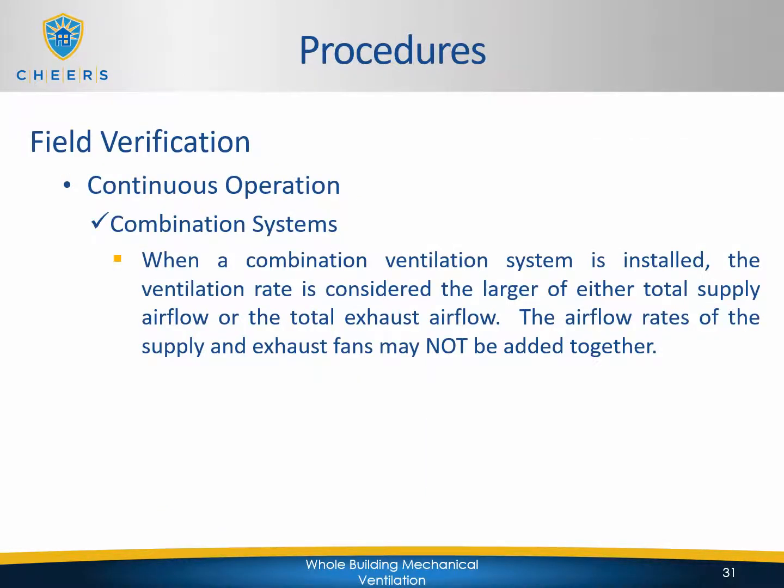If you're working with a combination system, when a combination ventilation system is installed, the ventilation rate is considered the larger of either total supply airflow or the total exhaust airflow. The airflow rates of the supply and exhaust fans may not be added together. You're just going to be using the greater one of the two.